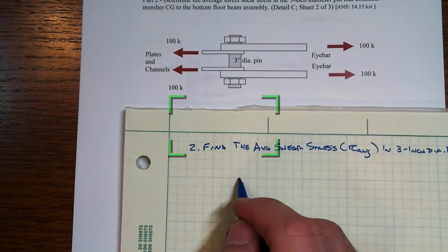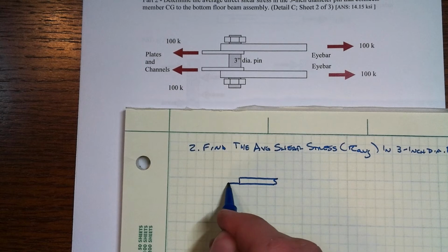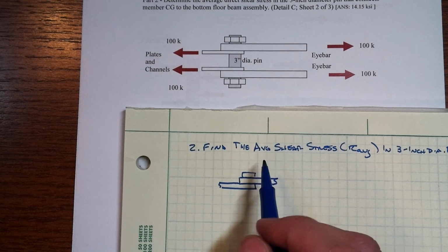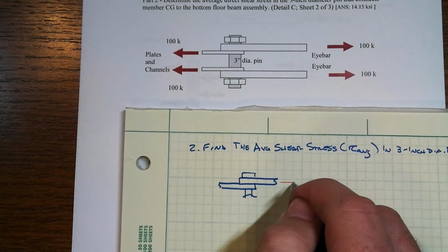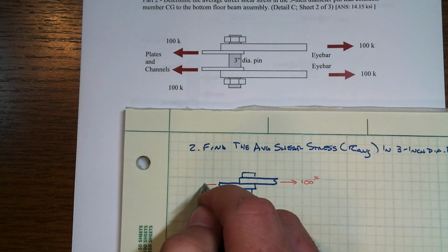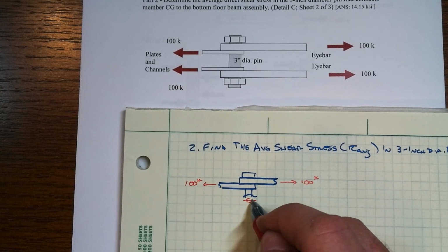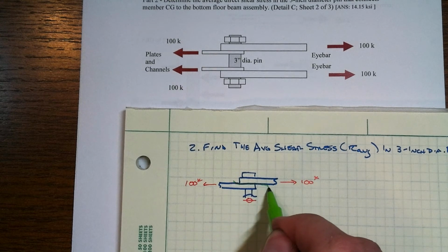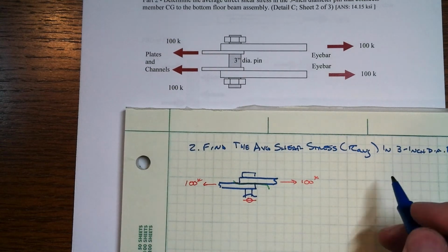Freeing everything out here, we'd have our I-bar, our plate and channel, the nut or head of the bolt, and then a portion of the bolt shaft coming through. Now, equilibrium-wise, we have an axial force of 100 kips in the I-bar and 100 kips in the plate that's attached, and that means there is no shear force on that bolt cross section right there. That's an important piece to understand. Now, if we walk our way back further and cut through the bolt in between those two pieces, that's called the shear plane, by the way.